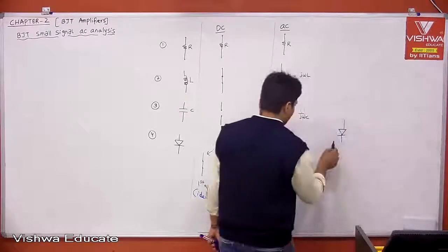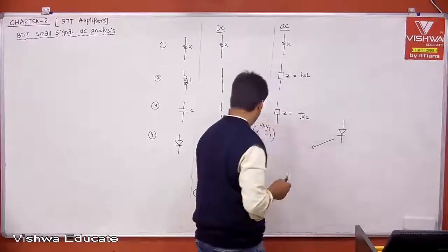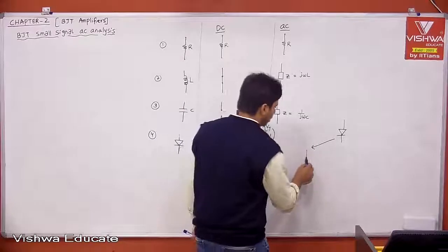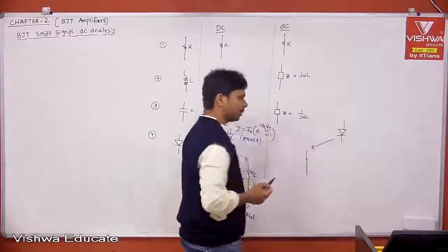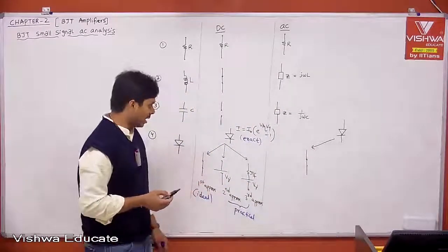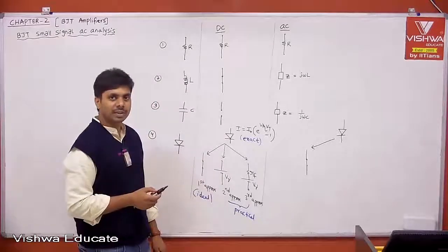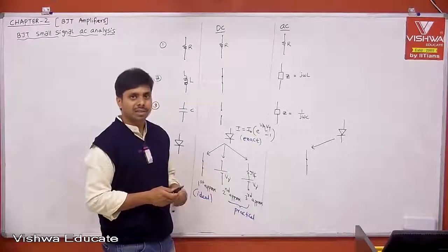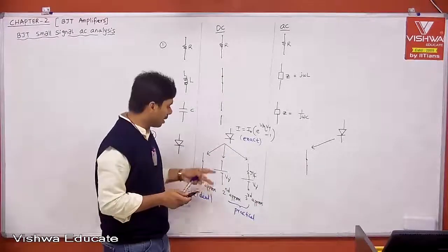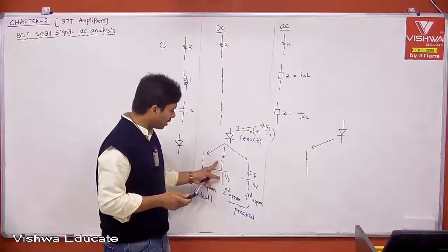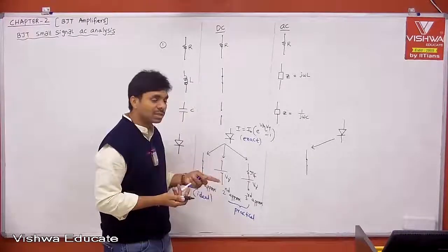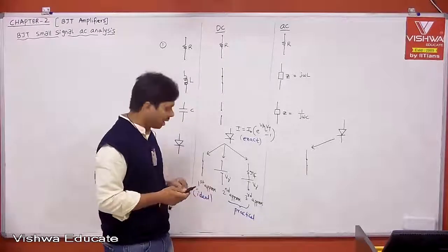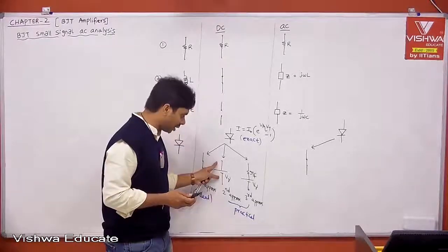Now coming to your first approximation, whether it is DC or AC, it is short only. Under AC analysis, then what about this? We have to replace it with its AC resistance or dynamic resistance. That is what we need to have. Therefore now tell me, what is this V gamma? V gamma will not change with respect to the frequency of the signal you are going to excite across your PN junction diode. Therefore V gamma will not change with respect to frequency.